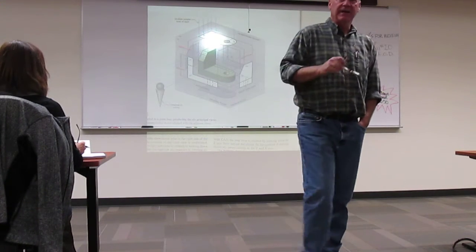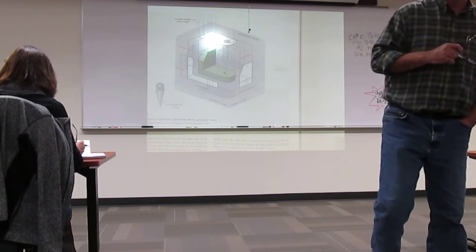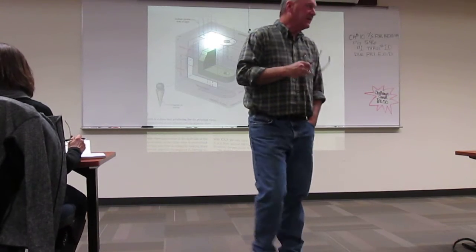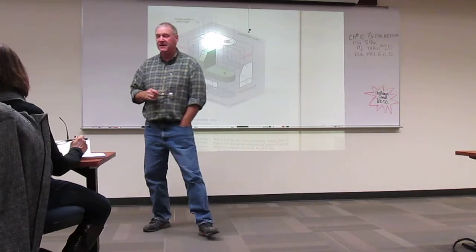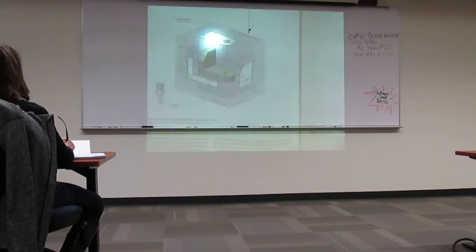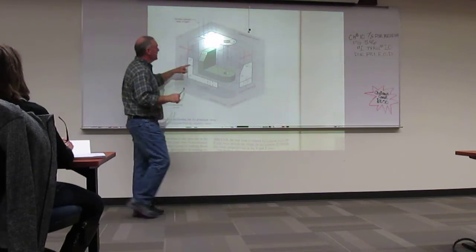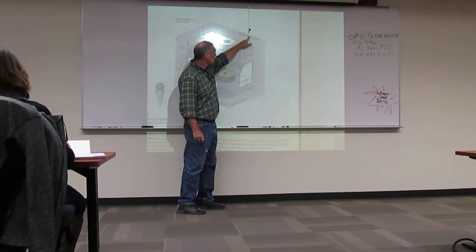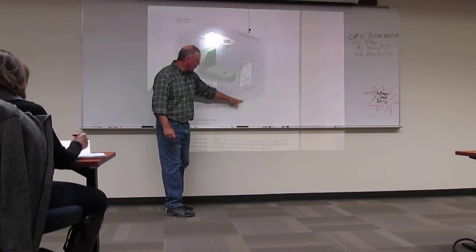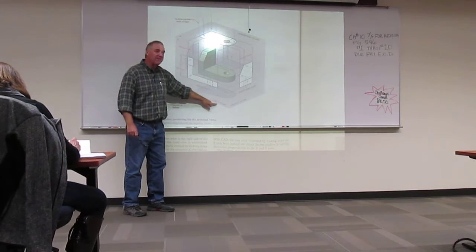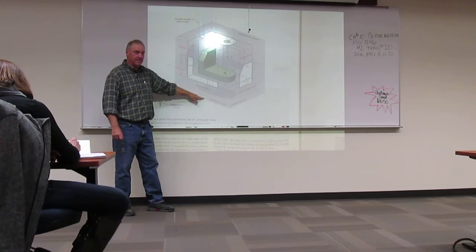Now, there are really only 3 planes of projection, and they create 6 views. The reason we want to go over these planes of projection is because the dimensions that are displayed with these planes of projection are important for us to know. So if you can look on here, you can see them labeled. There's a horizontal plane right here. We have a profile plane down here. And we have a frontal plane here.